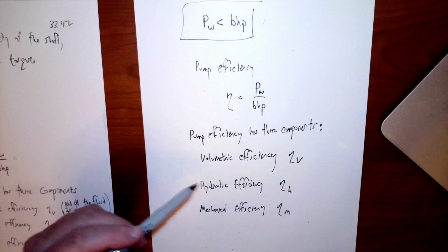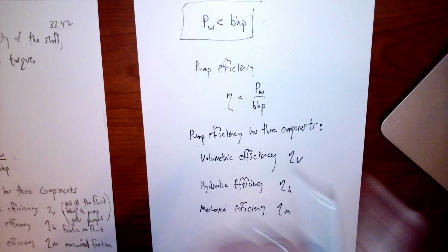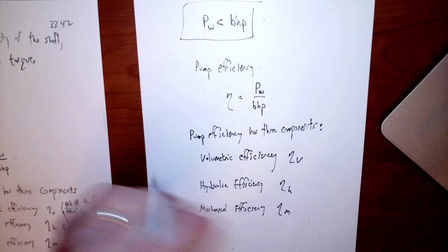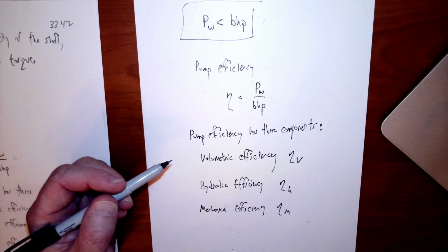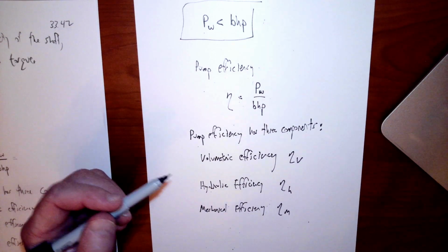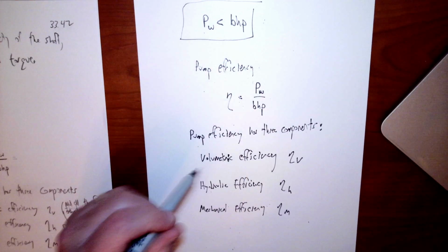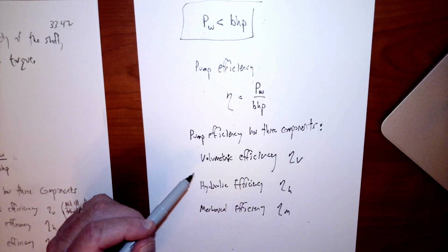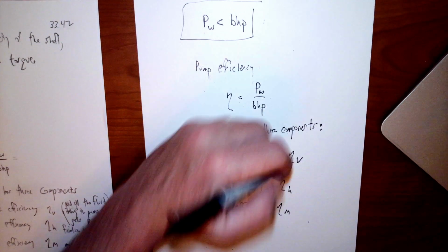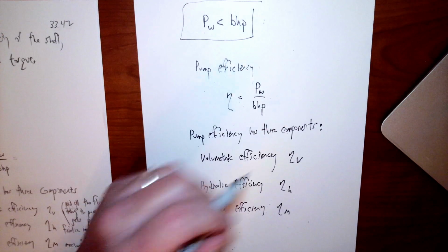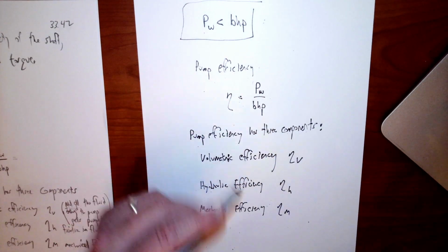Well, basically volumetric efficiency: if you're talking about a rotary pump where you had that vane spinning and you're trying to make the fluid move by rotating fan blades, some of the fluid doesn't really get pushed. It just recirculates, doesn't really leave the pump. Some of it may leak around the housing and not go out the outlet. I'm not talking about your pump being broken and leaking all over the place, although that would decrease its volumetric efficiency. But my understanding is also that some of the fluid may just be stuck in the pump. It's not in the flow field.